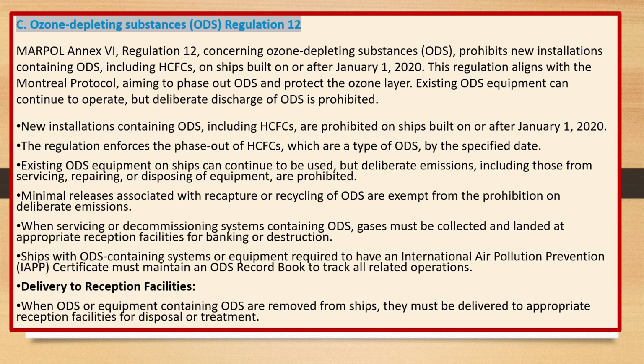C. MARPOL Annex VI, Regulation 12, concerning ozone-depleting substances, ODS, prohibits new installations containing ODS, including HCFCs, on ships built on or after January 1, 2020. This regulation aligns with the Montreal Protocol, aiming to phase out ODS and protect the ozone layer. Existing ODS equipment can continue to operate, but deliberate discharge of ODS is prohibited. The regulation enforces the phase-out of HCFCs, which are a type of ODS, by the specified date.